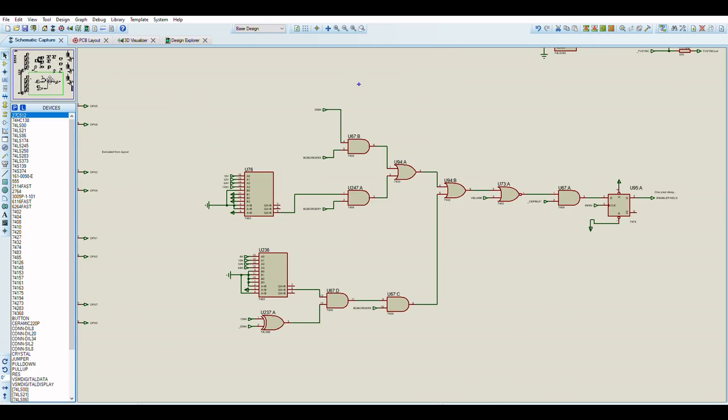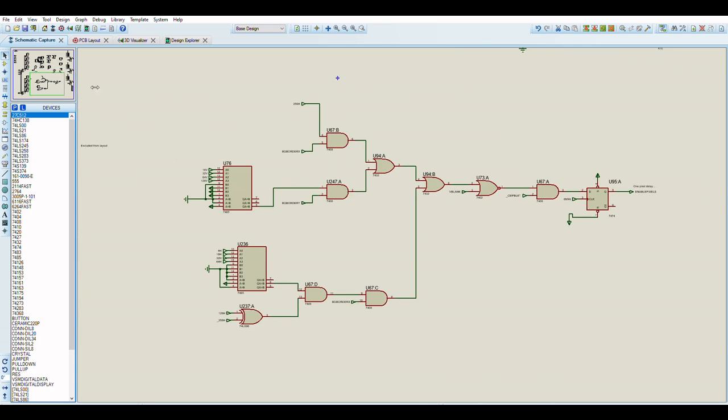So we have no overscan because you don't want to output pixel data when you should be going through H blank or V blank. On old displays, there is a potential that you can damage the display by trying to overscan too much. So it uses the vertical and the horizontal pixel positions with some comparators and some extra logic